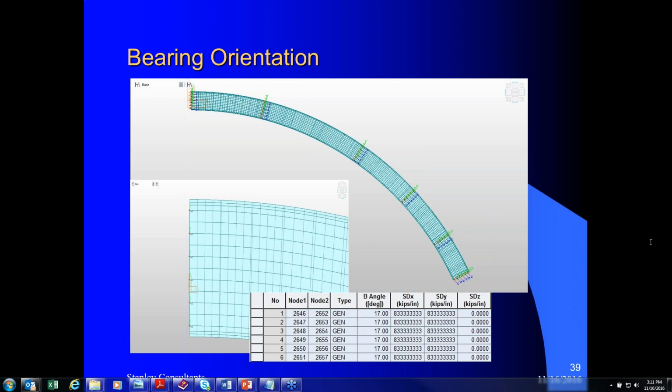Well, since we had a lot of cases, we applied the equivalent static loads. The question is, why increase the axle live load nodal loading for curvature? Does the model account for the effects of curvature? Because of the centrifugal forces, the outside wheel reactions are more than the inside wheel reactions.